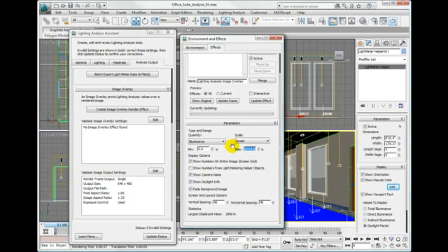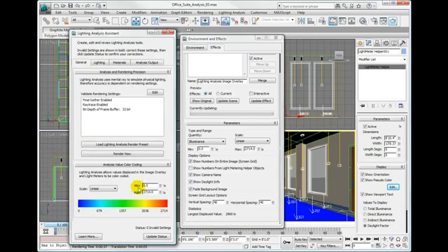Now we'll change our light meter color coding because that's no longer set. And if we go over to the General tab of the Lighting Analysis Assistant, you'll see that it has also changed the maximum value in the Analysis Value and Color Coding rollout under the General tab. So they are all connected. If you change the value here, it will also change the value in the Lighting Analysis Image Overlay Effect. Something very important to remember.